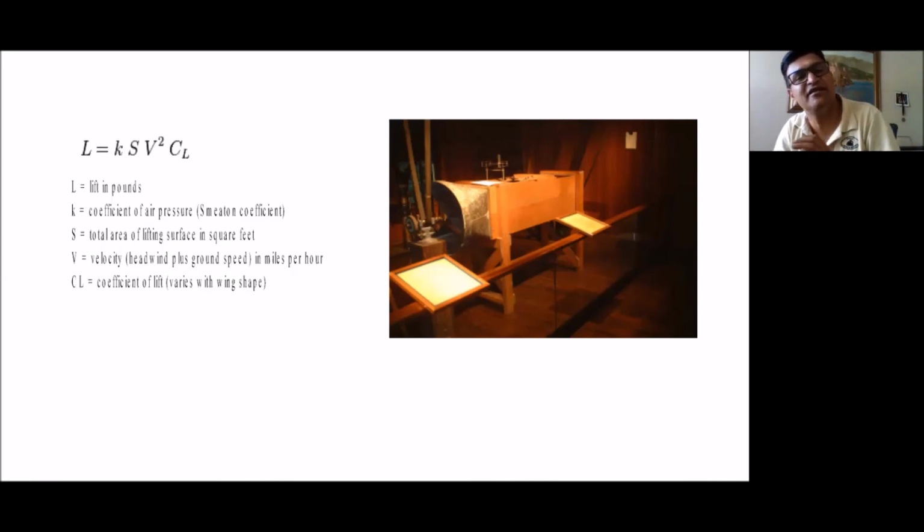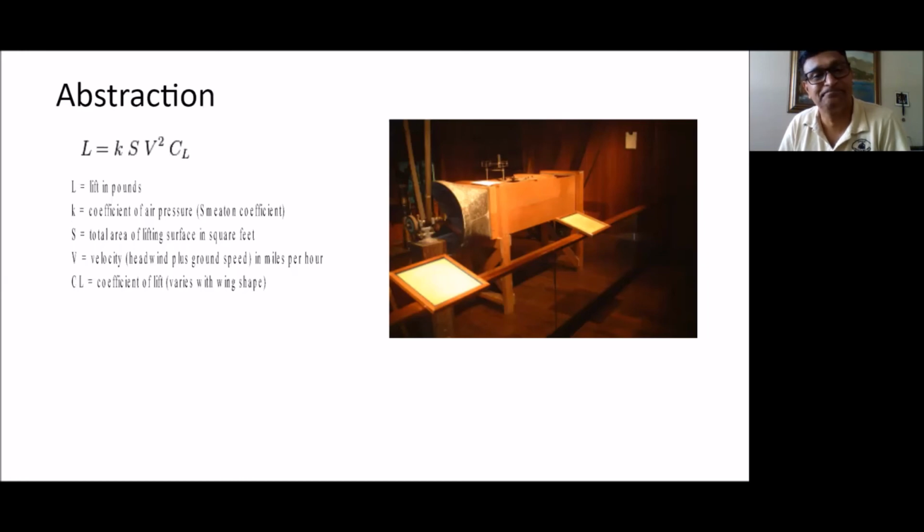If you see that instrument they built in 1901, it's unbelievable the way they built it. Wilbur and Orville built this wind tunnel, tested these wings, and understood that there was a big error in the coefficient of lift. They recalculated those coefficients and redesigned their flyer. In 1903, their flyer started flying properly. They got enough lift, and they knew how to control it.